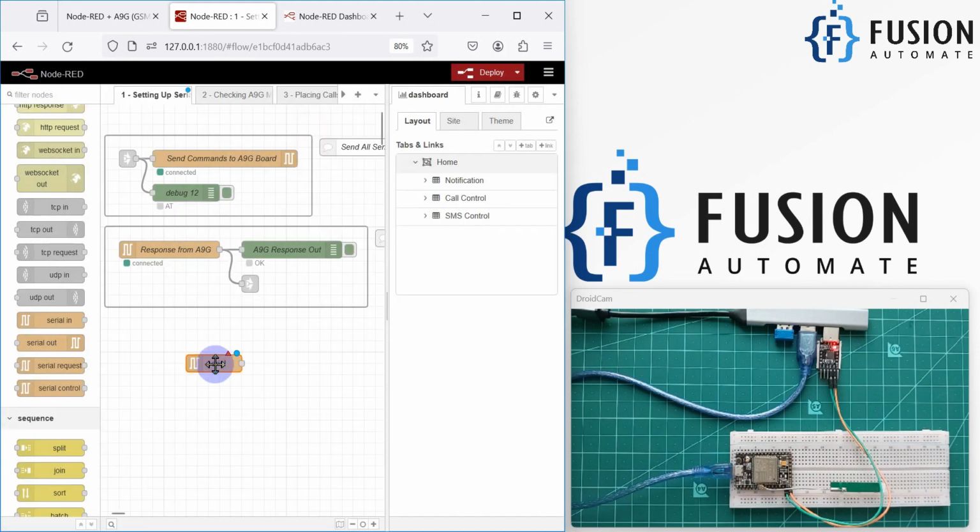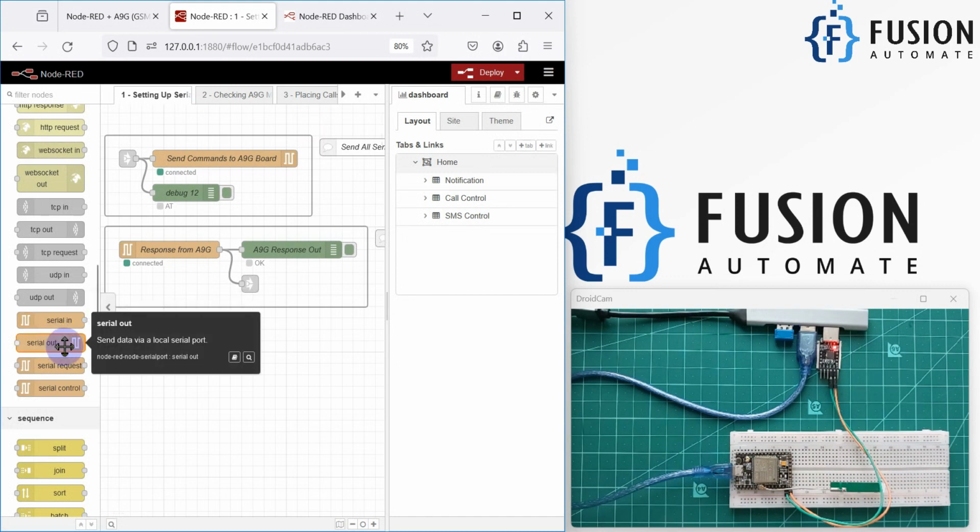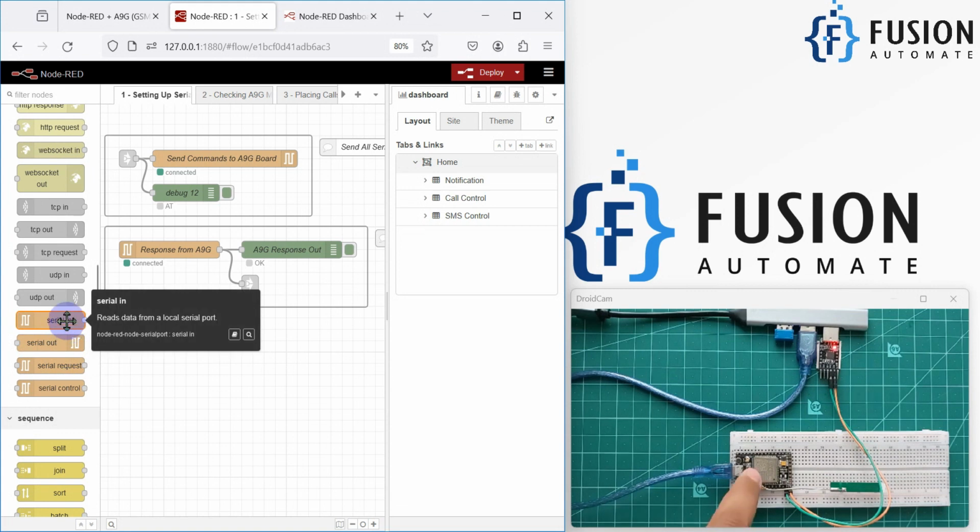I have used two nodes. The first one is serial in and the second one is serial out. You can see serial out will send data via a local serial port. So whatever AT command I want to send to this A9G board, I can send using the serial out node, and whatever response I want to read from the A9G board, I can read using the serial in node. You can see it says read data from a local serial port.